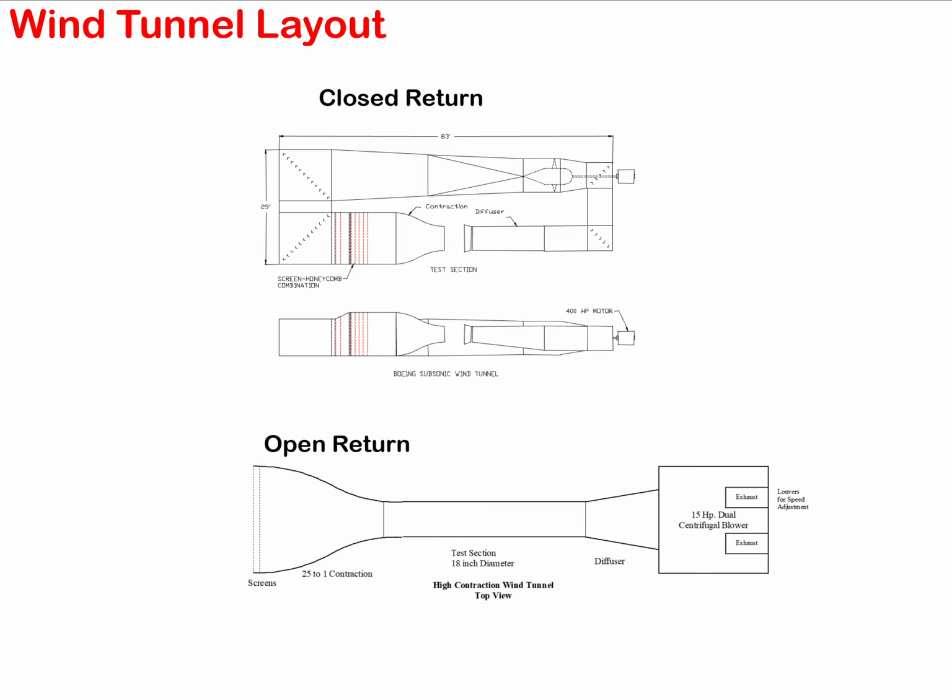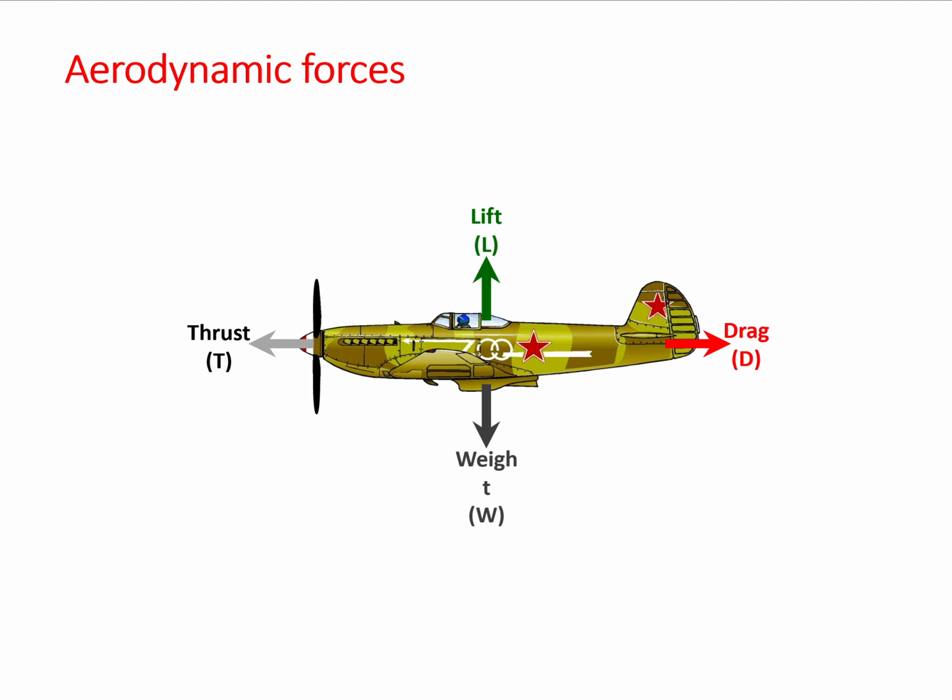But before talking about the scaling issue, let's talk about the aerodynamic forces first. The aerodynamic forces of interest to us, one of them is called lift, which is the force that is pushing your aircraft or your car upwards, and drag, which is pulling your aircraft back. So if you're sitting in an aircraft, generating lift is always beneficial because you want to be able to have a force that counteracts your weight. So you can fly, you can float in air or atmosphere, right?